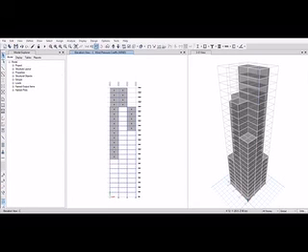In the elevation option, select section A and click on OK. Select all the shells using all story option.